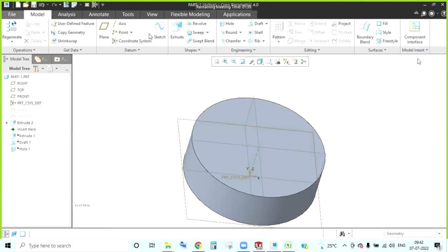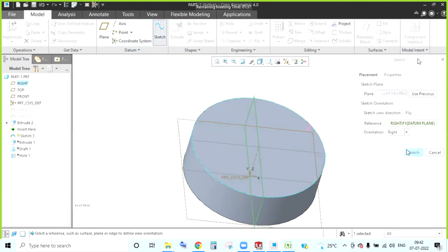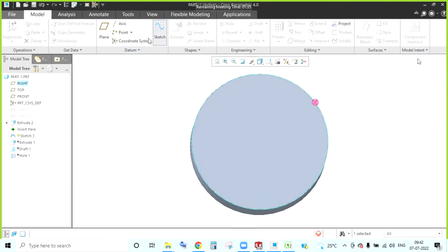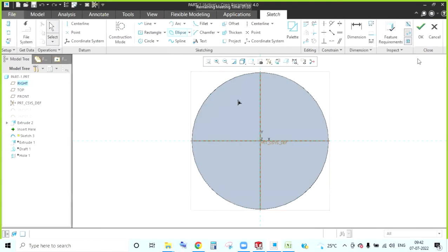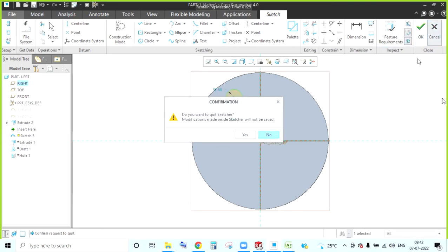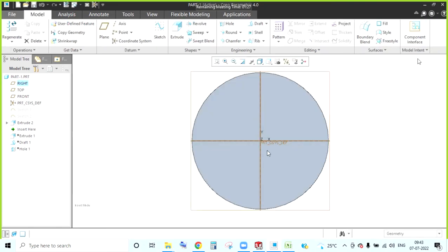Okay, done. Exercise. Select this. Go to sketch. Go with the sketch. Oh, no, no, no. Actually, I want to put the hole, right. My old habit. For a simple hole, I will not go for the hole option. I'll just go for extrude. That's a bad practice actually.